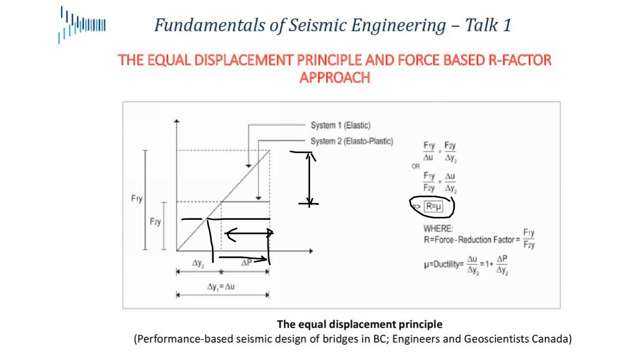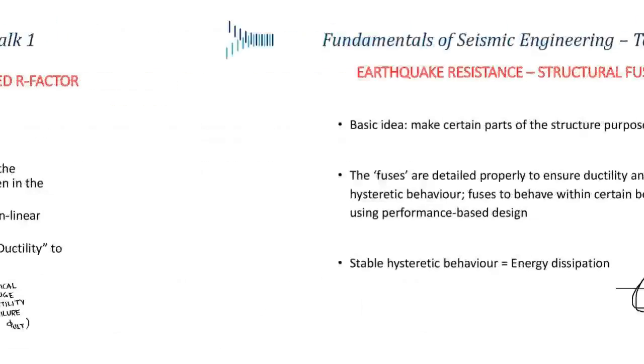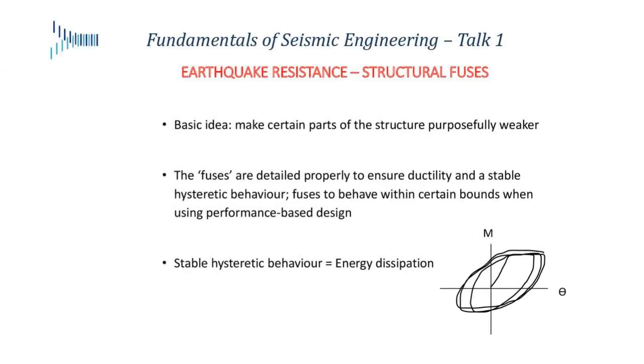You can see that my ductility here is larger than this value. Okay, so I can reduce the force. That's why I keep emphasizing, think about the displacement. Displacements and deformations is where the understanding has gone. That's where we are able to do sound designs. That's how things come about in a much better manner when it comes to seismic design. Force is important, but beyond that, we want to be able to think about deformations and displacements.